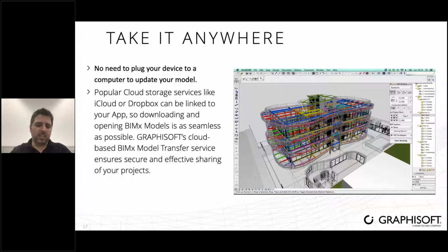For those who know Tekla, we used Tekla to color code the different profiles, which came in with the IFC in different colors. We tagged each one of these elements using the listing of ArchiCAD, put it in a container, and had it shipped, so that when they are assembled, they are properly tagged and properly numbered, so that they can be used in such a scenario.